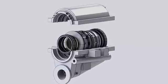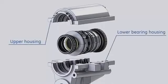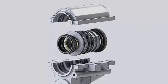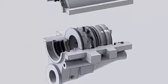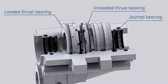The bearing components are installed inside the bearing housing, which consists of the lower and the upper halves. This bearing contains an elliptical journal bearing, loaded thrust bearing, and unloaded thrust bearing.